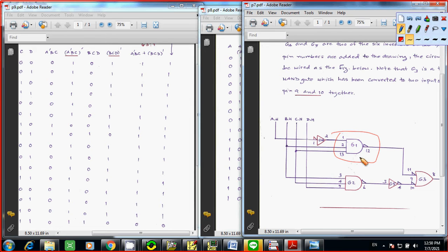or you use the NAND as AND and NAND as OR, right? So this one you're using IC 74HC10, right? That's the 3 input NAND gate.